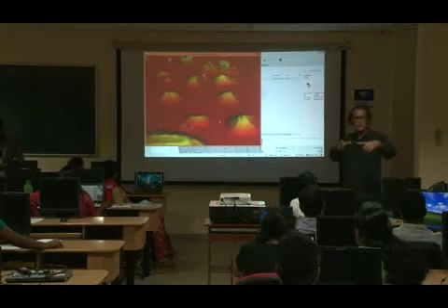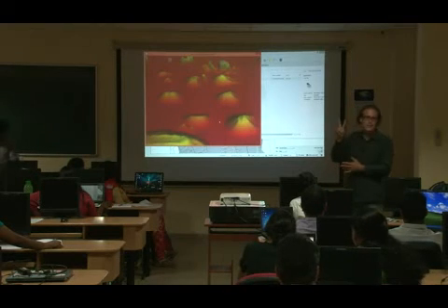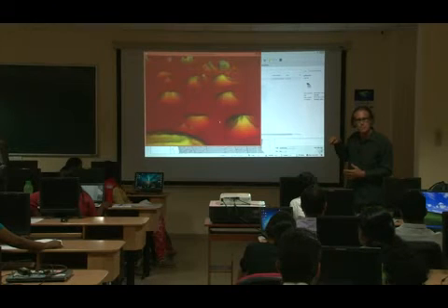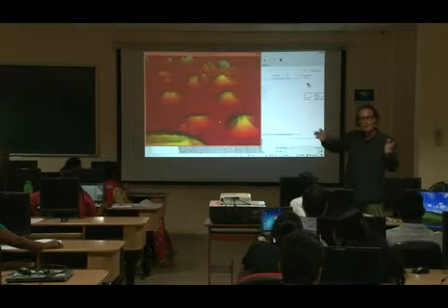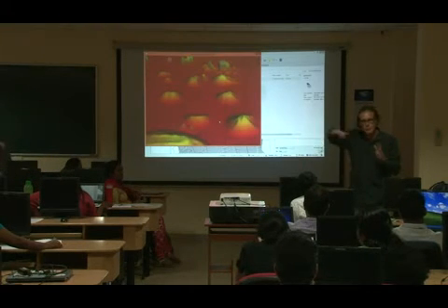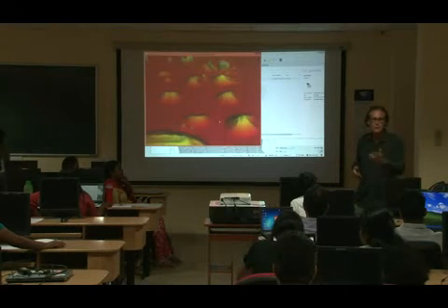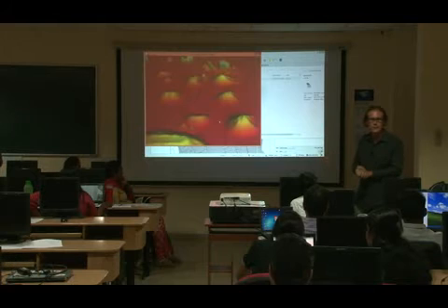You can just use the building footprints that exist already in shapefiles, and 2 of our states are now open data. You can download every building footprint just by going to the webpage, including every parcel and every Liegenschaft, which is a bigger area grouped together, and pretty much every other thing. Even LOD 1 and 2 CityGML buildings, all open data for the entire state.